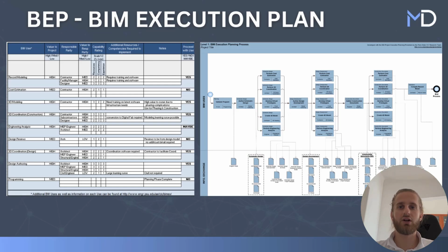The second chart is filled out by each stakeholder separately, depending on what needs to be delivered. For instance, if a 4D model is to be delivered, it is typically done by a civil engineer. After the architect provides the architectural model, the civil engineer must insert a time plan and integrate these pieces of information together to produce a 4D BIM model. However, questions arise. Has the engineer done this before? They may have worked on 3D models and time